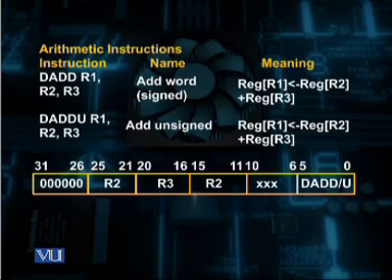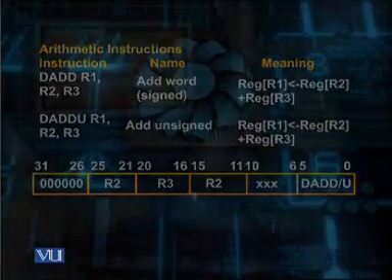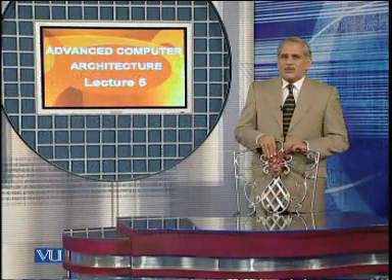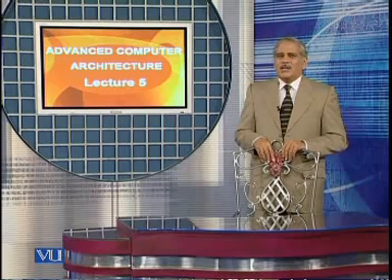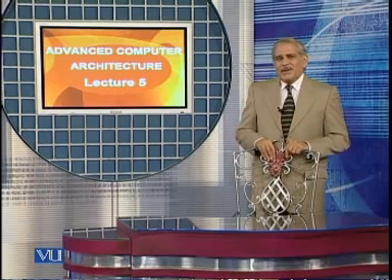Please note over here the difference in the sequence when an instruction is written in assembly language and when it is written in the instruction word over here. As you can see from here, the sequence is while moving from left to right. In case of the assembly language program, first we write the destination address and then we write the source operand addresses.